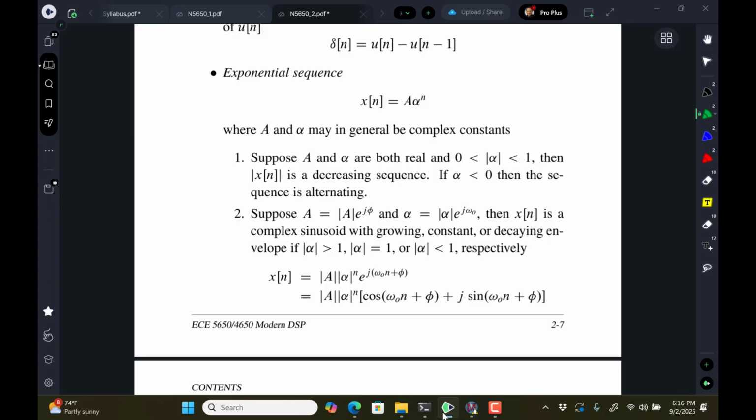We could later change it with a unit step function to start at n equals 0, or any of those things. But this is getting you into the idea of a discrete time sinusoid. Because sinusoids, as you first learn about them, start at minus infinity and go up to plus infinity. They're just sort of a signal that's been running for a long time.